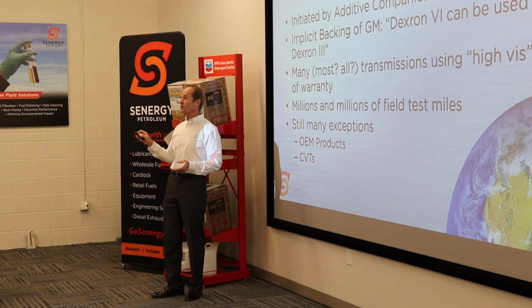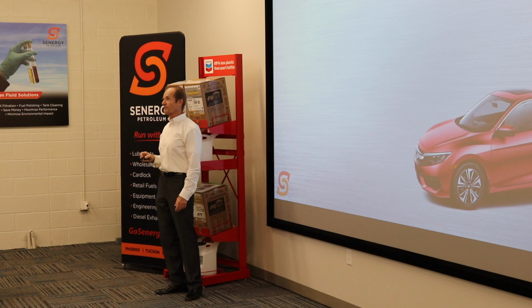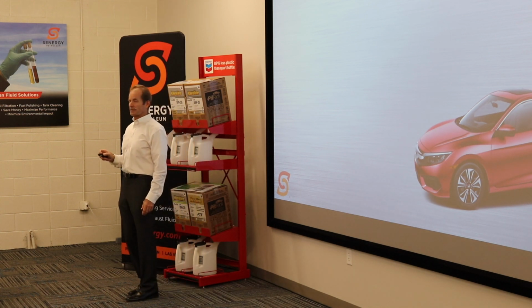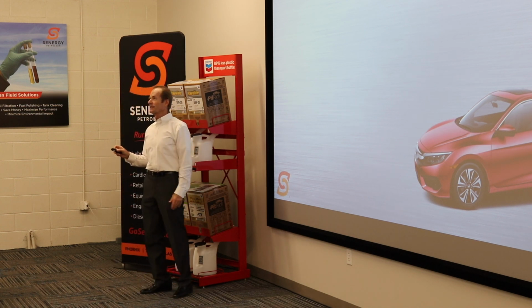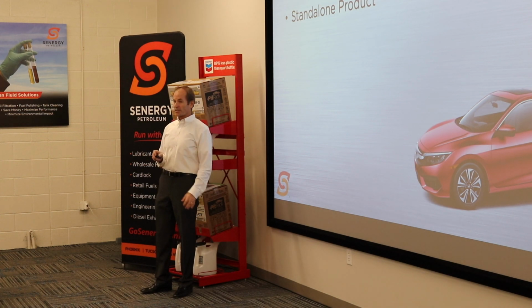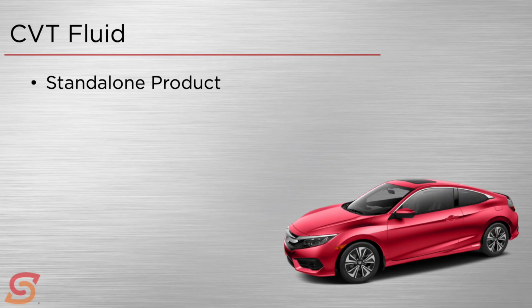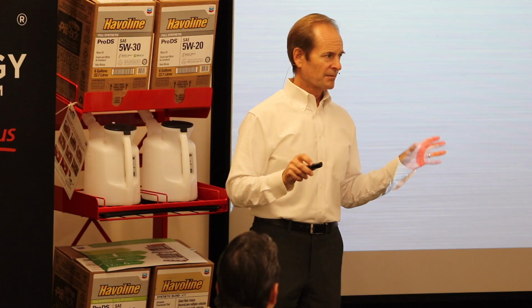All right, and that does lead me to talk about CVT fluids real briefly. CVT fluids, I mentioned, started in small vehicles. Now Toyota Camrys can come with CVTs in them. This is sold generally as a standalone product, so they're not trying to make it meet anything else other than be a CVT fluid, although they do have it meet CVT requirements from a number of different OEMs. Okay, I know of none that aren't full synthetic. There may be some out there, but the